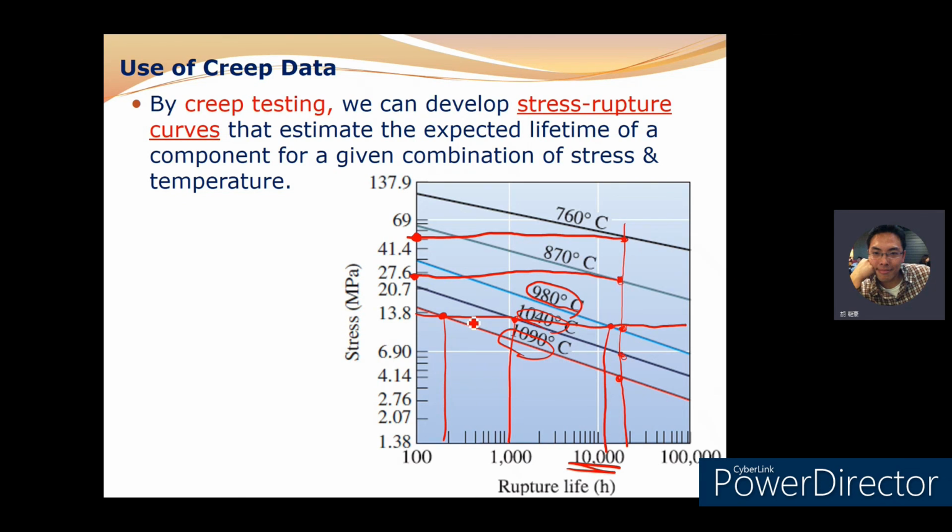You can see the stress is getting smaller and smaller with increased temperature. Therefore, if this material is heat treated at 460 Celsius and we already design its rupture time, you know the applied stress for this mechanical part cannot be beyond this applied stress.